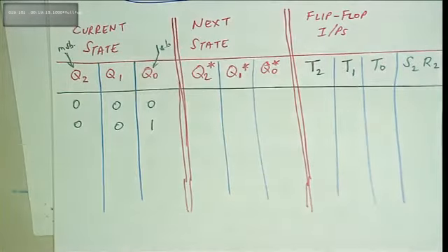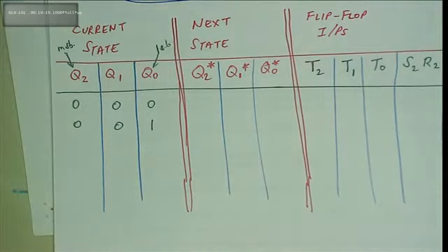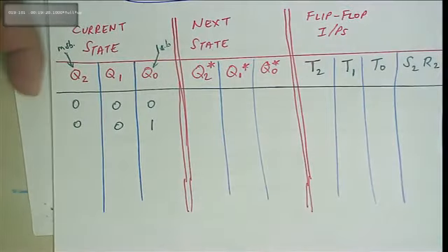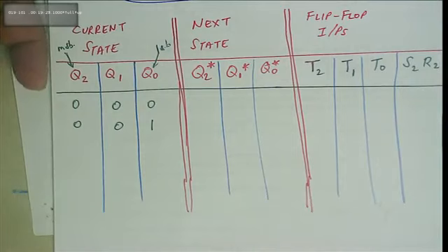Just to let you know, if there was a direction bit over here, let's say an X input to control the direction, X is 0, it goes forward, X is 1, it goes reverse. How many possible combinations would you have had? 16. There would have been another title over here called the system input. Remember that one? So what is different about our state table compared to your project state table? You have a direction bit, so that adds to your possible combinations on the left hand side.